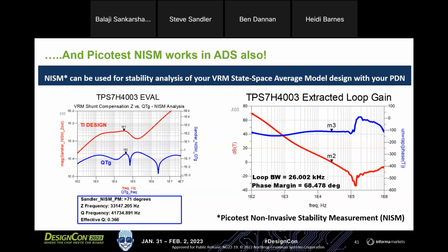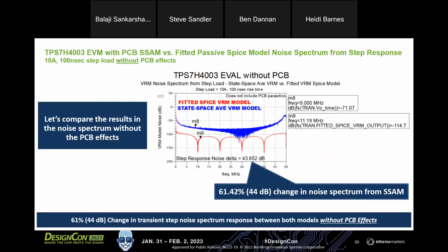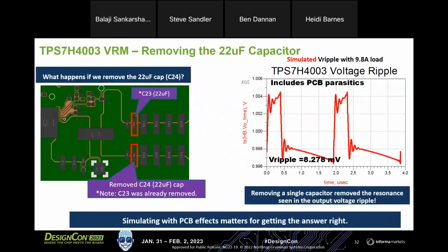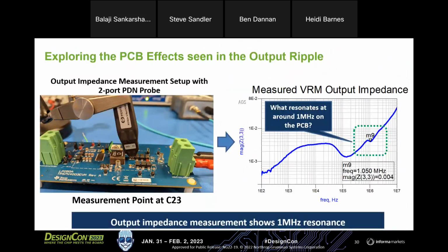One last thing I want to cover is that Arif asked if we could go over how the output impedance measurements are made for on and off. And I think I explained the on and off, but I don't think I explained how they're made. The traditional measurement for these low voltage core power rails is called a two-port shunt through measurement.